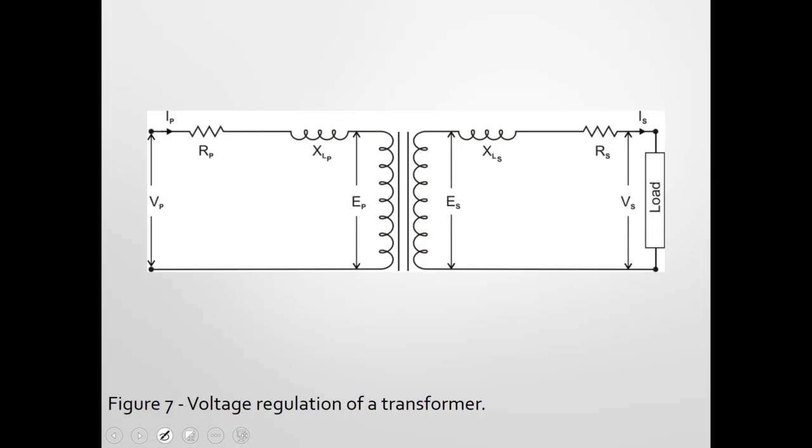All right, so now that brings us to voltage regulation of a transformer. I do have one example of a calculation here. So if you recall back in first period, you guys learned about batteries and you put them under load. So we did an open circuit voltage of a battery. It was like 13.2 volts, like on a 12-volt battery. Let's say we had a car battery. And then we put it under load, and as we put it under more load, we'd see that the terminal voltage would change. And that was due to internal resistance within that battery. So it would have an internal volt drop.